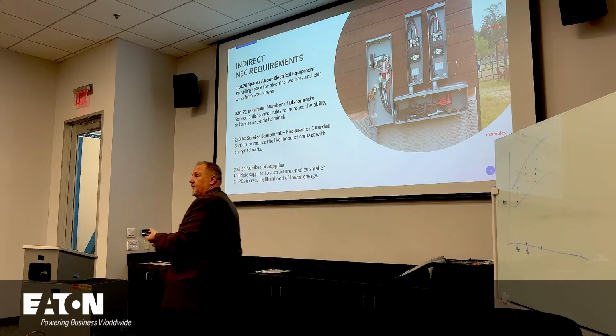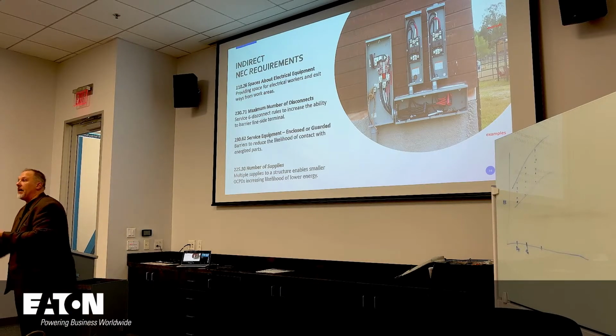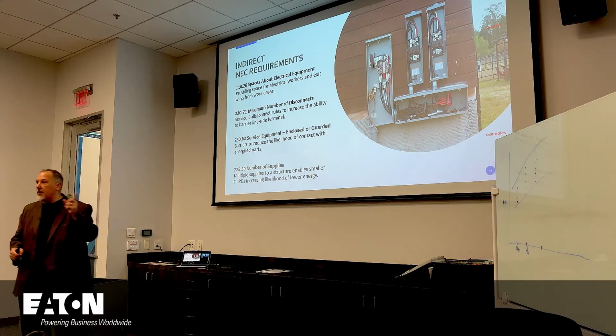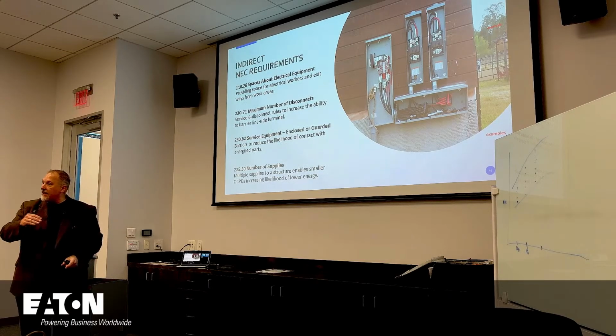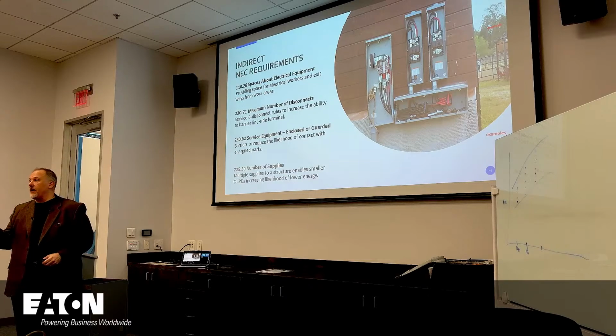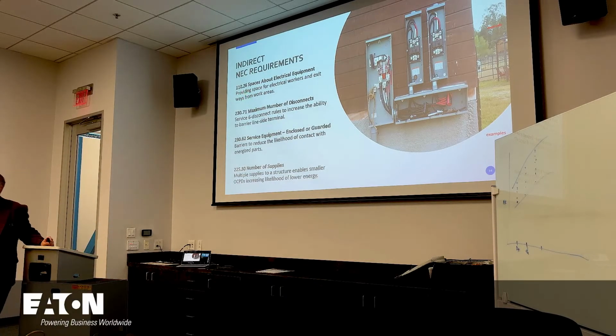Working space, barriers, right? You have working space requirements, we have barrier requirements in the NEC. All of those address likelihood of us accidentally coming in contact. Has nothing to do with severity whatsoever. So we have 110.26 spaces. We got to give our electrical workers space.